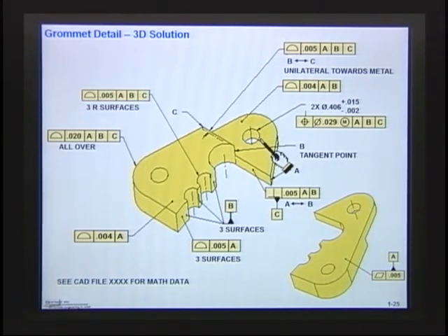And then that was the position tolerance we put on the holes. See, there's your position tolerance. And then let's see, what else did we do? I guess what else we did is we located this top surface. Remember? We said that had a profile within 4, and then all around, everything else that wasn't covered, all up around here, had a general tolerance, and that said it was profiled within 20 thousandths. And that was all over then. All right, so this gives you an idea how you might tolerance a solid model.